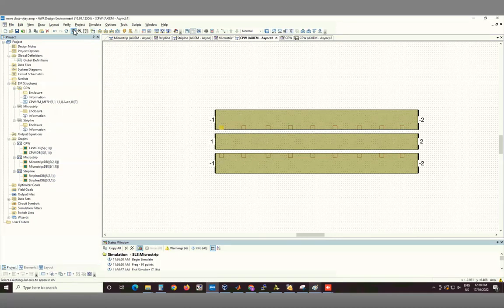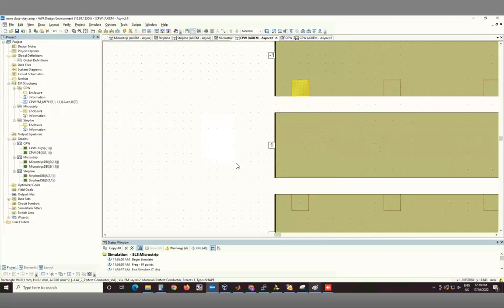But in order to complete the connection, I have to put something across. Earlier the ground plane was serving the purpose of connecting the two sides, but we don't have anything to do that right now. So I need to make another metal. The way you do it is draw one across it like this. Just move it aside here.